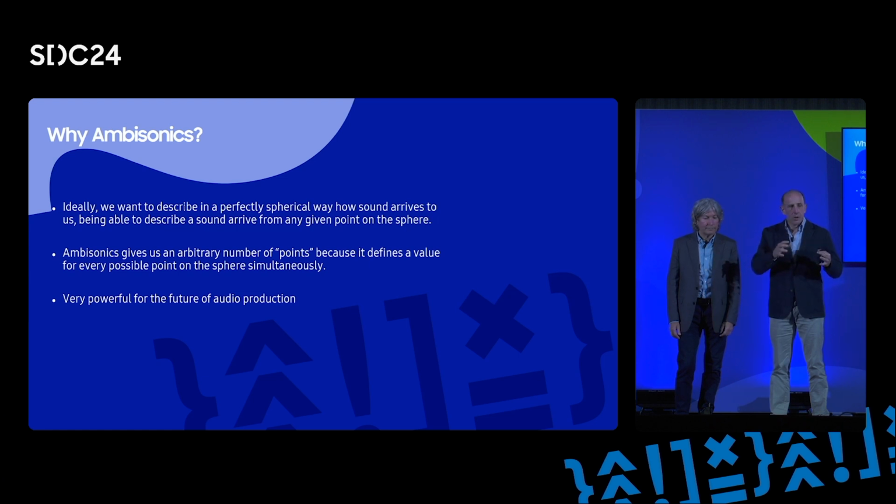One of the other audio elements, rather, when you look at the other solutions out there, and there are very good solutions in the market that support immersive audio, they tend to use as their key tool object-based coding. Object-based coding does a very good job of representing an object in an audio space, but with every new object that you add, you're increasing data rate. So you will hear about solutions talking about supporting up to over 100 objects, but each of those objects linearly scales the data rate.